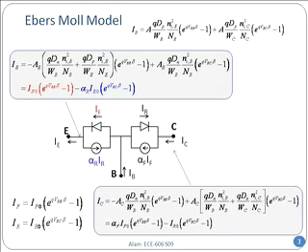Now in here I have multiplied with A_E, area of the emitter, and in the bottom, area of the collector, A_C, because the emitter area and the collector area need not be the same. Remember the double diffused junction? You had these three layers. On the top, the emitter was tiny, coming from the top, and the collector was big. So the two areas need not always be the same, but for the simple analysis, we'll assume that they are about the same.